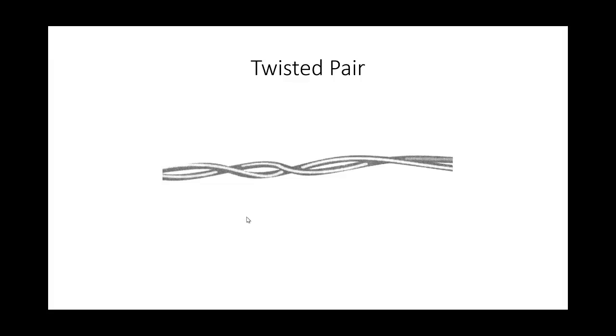The wires are twisted together to minimize the effects of electromagnetic interference. The effect of any current induced in one wire of the pair will be cancelled out by that induced in the other, as long as the wires are close together. One of the main sources of interference in a twisted pair cable is neighbouring wire pairs, which can radiate away some of the energy from their signals, and this form of interference is called crosstalk.